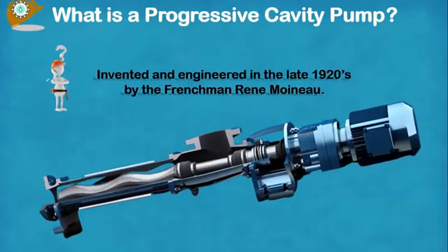The progressing cavity pump was invented as a supercharger for an airplane engine by Dr. René Moineau following World War I. Due to the multi-phase and high suction capability of the pump and its ability to convey large quantities of air, vapor, or gas in a fluid, which may also contain solids, this pump is not usually used in the same way or considered to be the same as other rotary positive displacement pumps. The progressing cavity pump was designed as a combination of a rotary pump and a piston pump. It represents an integration of the specific advantages of both types of pump constructions. Other terms for progressive cavity pumps are cavity pumps, prog cavity pumps, and PC pumps.